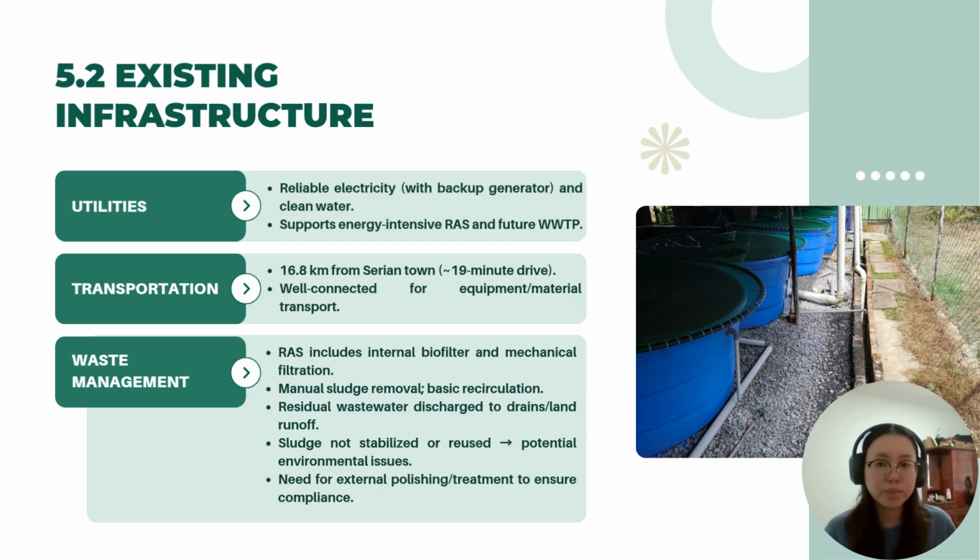Next is the waste management. Here is where it gets interesting. PGA uses manual sludge lifting and basic waste recirculation inside the RAS. The biofilter reduces some nutrients, but residual wastewater still needs to be discharged, and right now that goes into the drainage system or sometimes onto land as runoff.